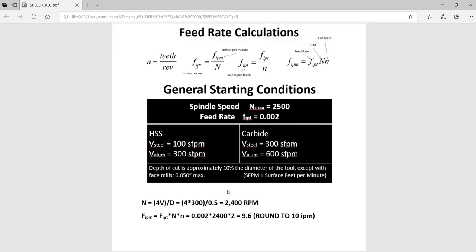Now in the lab, we're used to cutting closer to 1600 to 1800. We do that in CAD/CAM and in 1000 for safety. If a part gets chucked out of a lathe, it's a lot safer to have it do it when that spindle's spinning a little bit slower. So that's the reason why we have a discrepancy here.